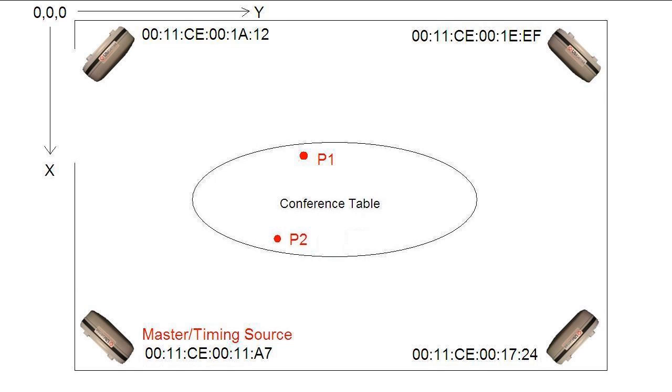If you don't have a total station to accurately measure your sensor locations, the location engine has a handy tool called the Survey Point Finder that can help you determine the locations of your sensors or tags with fairly decent accuracy. The general idea is that if you know 2 points within your space, you can easily determine an unknown point, like a sensor for example.